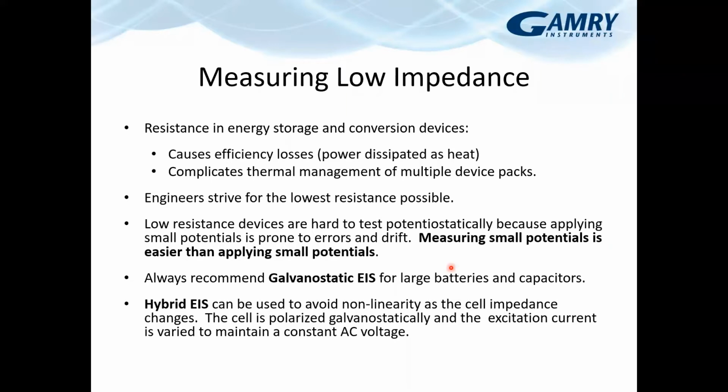For that type of system, even though the high frequency component may be slightly better to measure galvanostatically, that current signal that you use there might be too large for the lower frequency, higher impedance. So the exact transition is kind of tough to gauge.